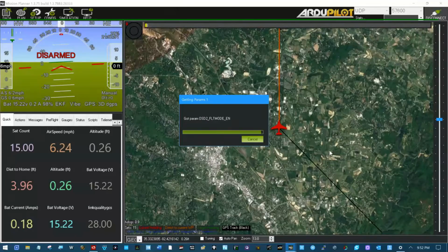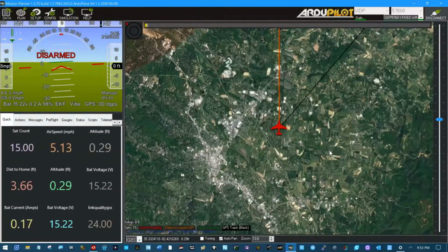So when you look at a Yagi antenna that is 13 dB gain, that antenna could take you out 4 times as far. If you divide it by 3, 3 fours are 12, throw the other one away. It's not going to do much for you. It'll do a third of another doubling. That simple 13 dB antenna will really let you step out there some more.